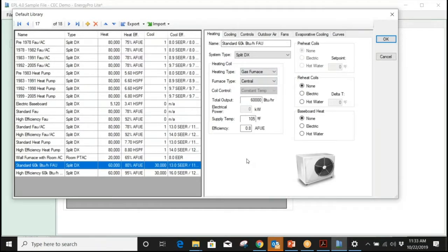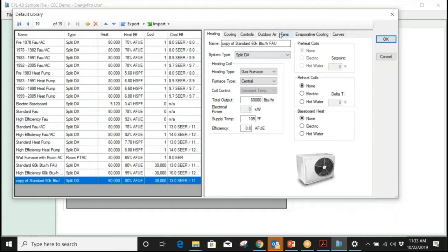If you're on site and you're going into the units and you're doing what you should be doing and getting the model info for it, you might find that you're not finding the specific make or specifications of the model that you're seeing on site. You would just pick whatever's closest, hit the plus button, and then modify what you have here to match on-site conditions.